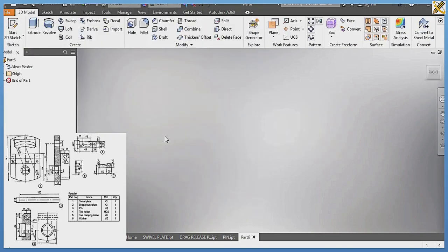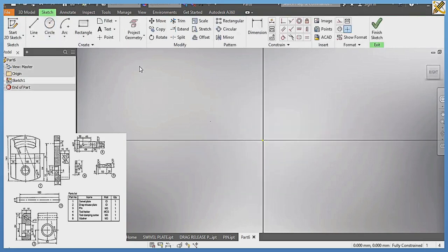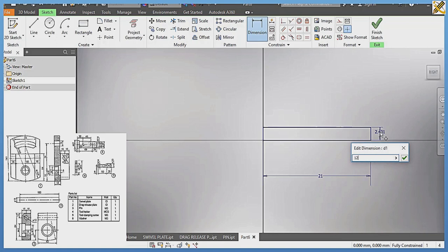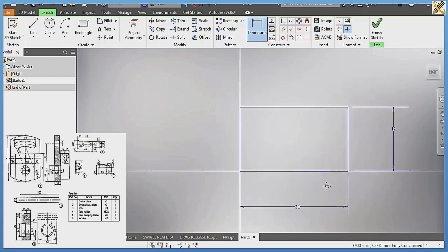For the fourth component, all right, this first component we will actually revolve. We are going to apply revolve, because it is not a perfect cylindrical part. Okay, so picking my line, standing right here, coming right here, to the bottom there. So I label this as 42 divided by 2. That will be this in there. I label this height as 12. It is indicated in the question, right?